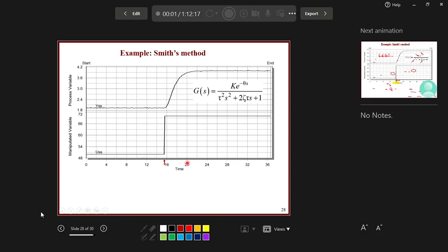Okay, so this is the same example we used before to model a first order process, but now we will use it to approximate a second order process. Now, when should we use a first order and when should we use a second order? Actually, we always prefer to use a simpler model, a first order. However, if the response has some form of second order behavior, like for example here you can see at the beginning the increase in y is not sudden like the first order, this is an indication of an S-shaped model, which means that it is higher order.